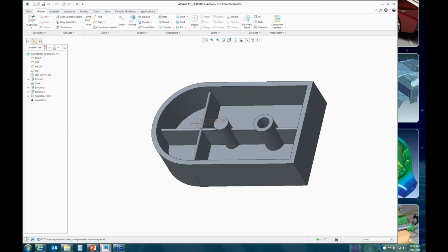Okay, I'm going to go ahead and redefine that. And the reason I want to do that is I really don't like the way I created the sketch. If I edit this rib, you see I have these dimensions here that really don't go anywhere. So that really bothers me when it comes to making a drawing. I've got extra dimensions in my model that I would never put on a drawing. And also, it opens up the rib for failures, all right, because we have these dimensions now. If I change the size of my model and the rib ends up outside, it will fail.